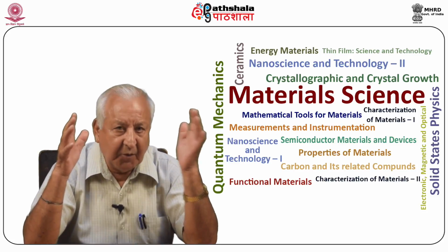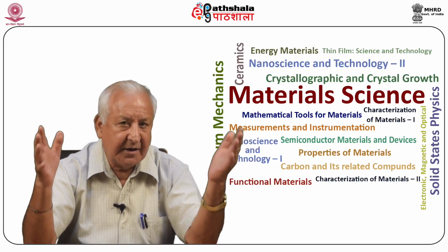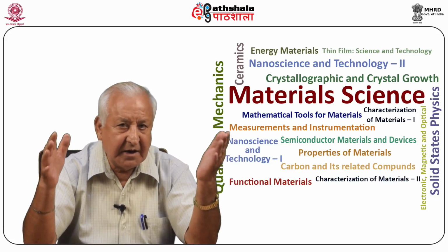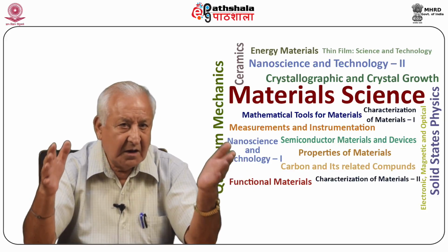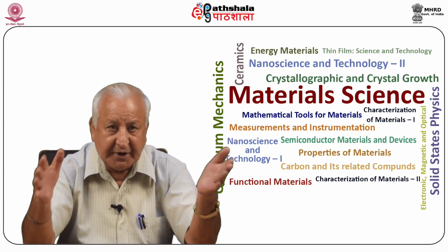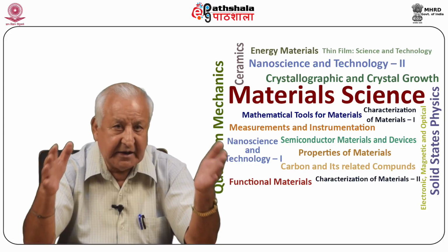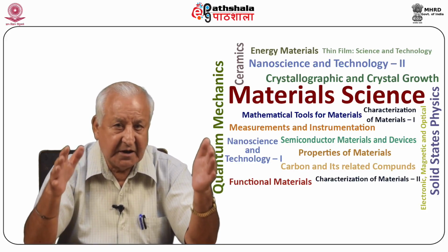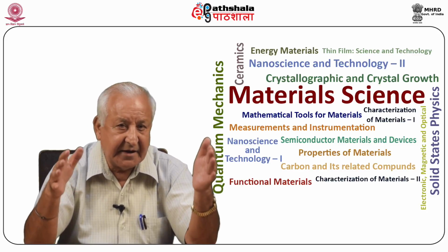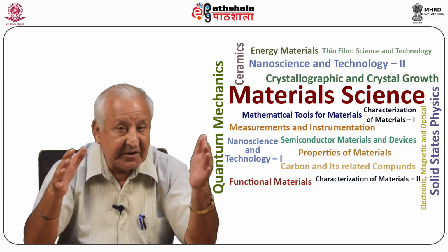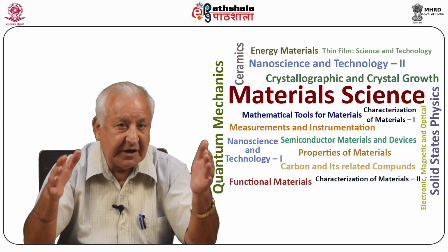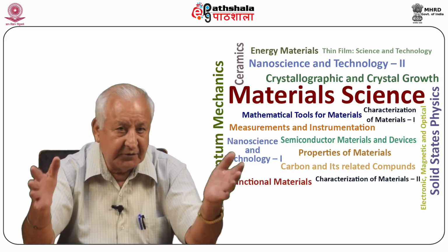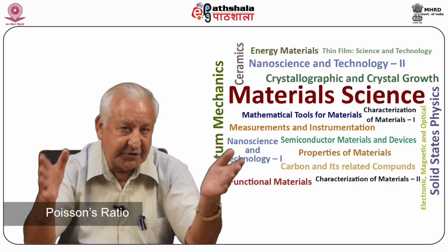Here, the positive values of sigma refer to tension and negative values of sigma refer to compression. Sigma phi phi is a compression or tension acting in a plane perpendicular to r. The shear stress tau r phi acts in a radial direction. Capital G stands for shear modulus or modulus of rigidity, and nu stands for Poisson's ratio.